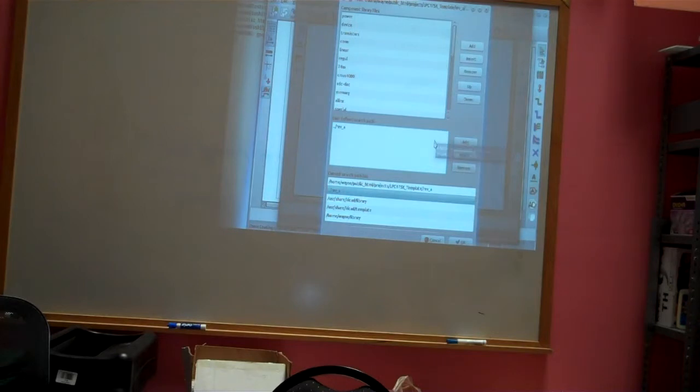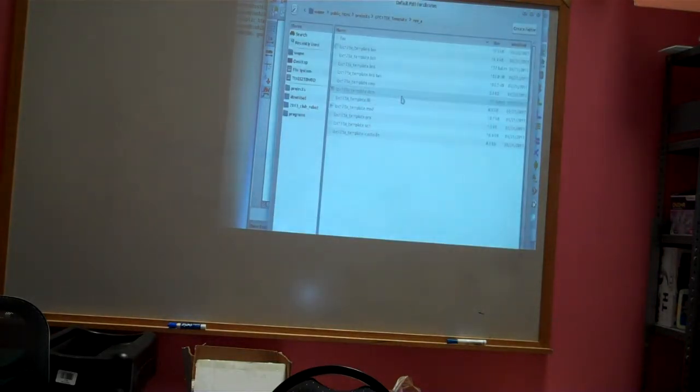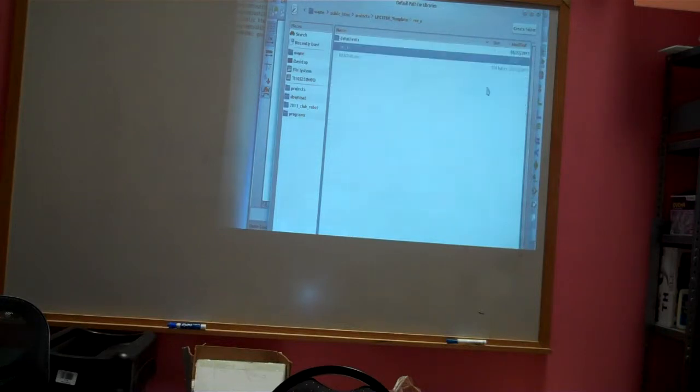And there's two things going on here. There is, over here where my mouse is, the directories in which to look for libraries. Okay? And there's these down here, and then these are the ones that the user can add. So you have the hard-coded ones that they'll give you no matter what, and then you can add ones. Whenever you add a library, and I will do that just to show it to you, we're going to click Add, and it's going to pop up a window, and I'm going to add one level up.